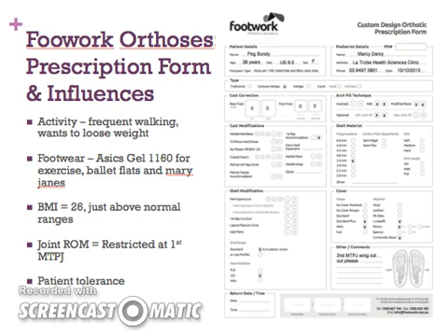Polypropylene is a firm yet flexible material that is available in a variety of thicknesses, ranging from 2 mm to 6 mm thick. We decided to use a thickness of 3.5 mm for Peg, as she needs flexibility in the orthosis for her exercise. However, she has a slightly high BMI, so choosing a thicker material that will not fully collapse under her body weight is suggested. This in turn will help Peg be able to tolerate the device and increase compliance when wearing it.